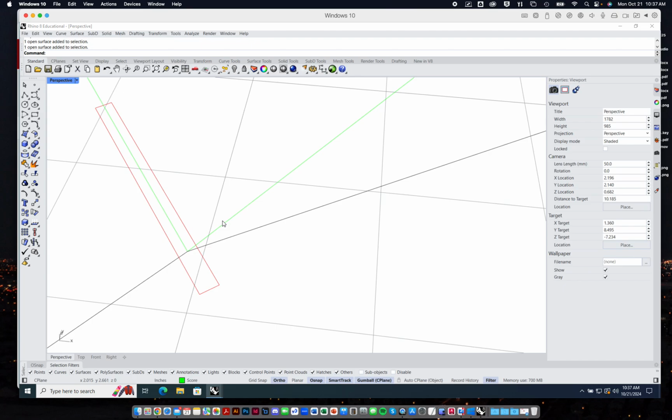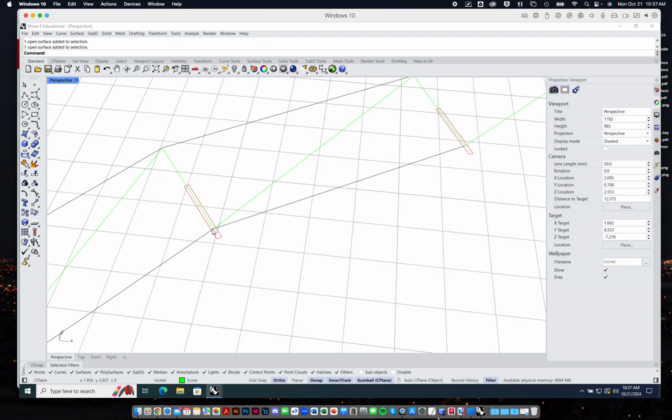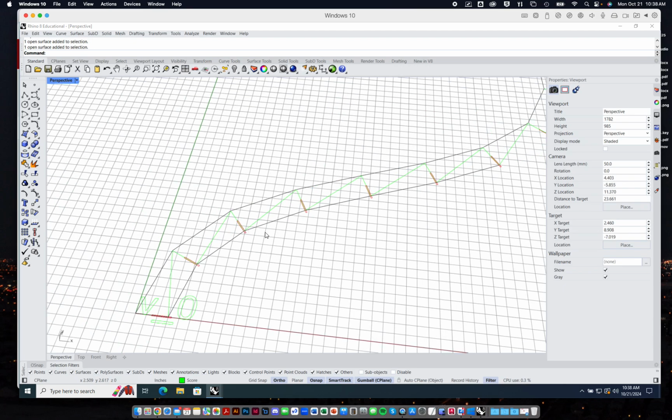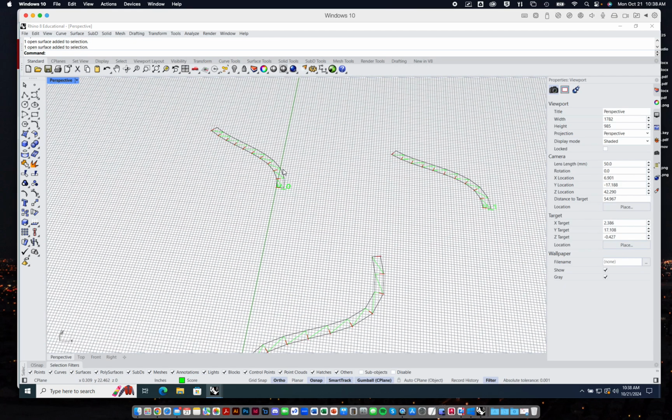you'll see here that it also has some through cut curves, right? Like you just made a box for the notches, right? In other words, it was easier and quicker to just make a notch than to try to get everything to trim out. It'll still cut those notches. And look at this, right? It cuts those notches in one direction in U and in the other direction in V so that they really will go together.